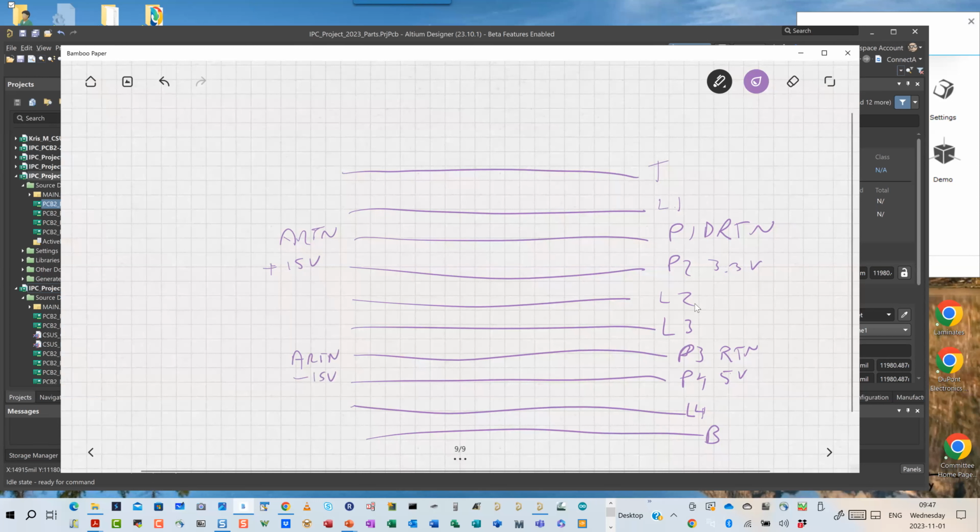Again, this is just one possible structure. In both cases, what you'll see in signal integrity is that for every power plane, I want a return plane directly adjacent to it, so I form the planar capacitance I need for the high-speed switching, which we'll talk about during signal integrity if we have not already. Same thing over here, even though I'm not as reliant on the planar capacitance, having it there for high-frequency noise is always a good thing. So this is going to be my plan for layer distribution here.